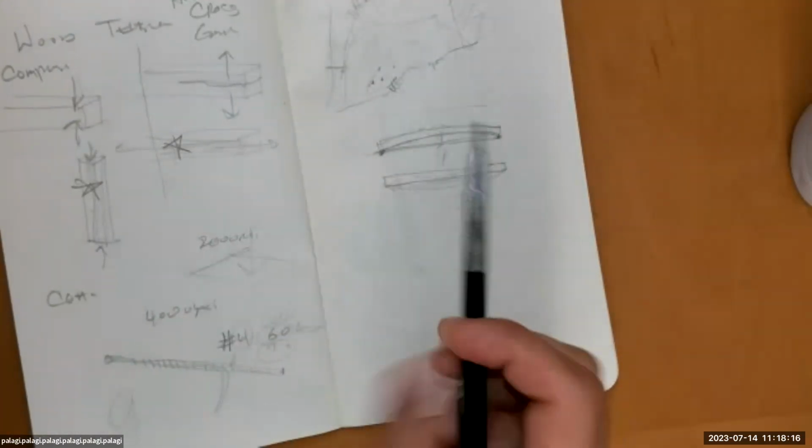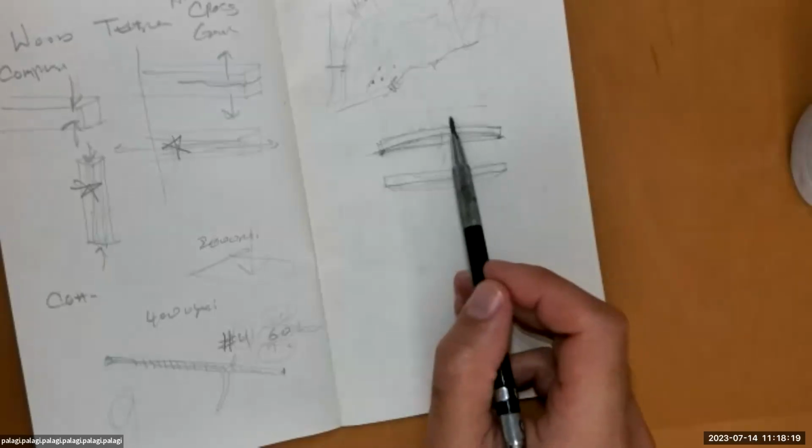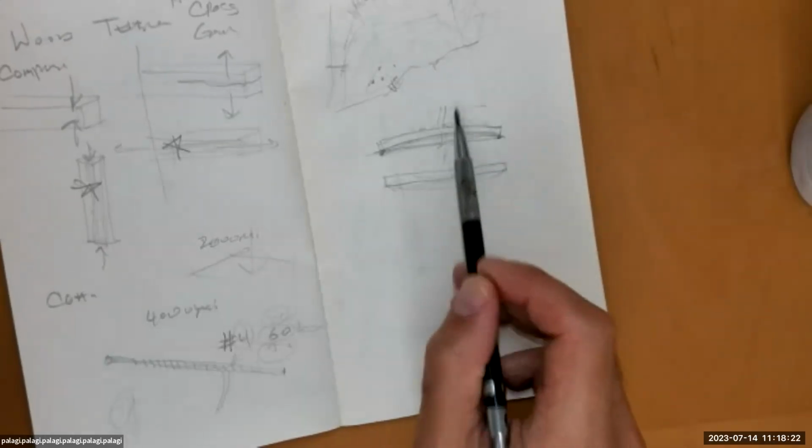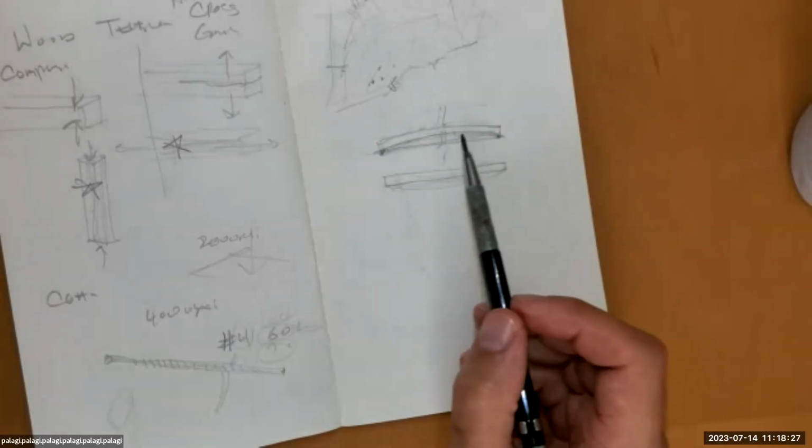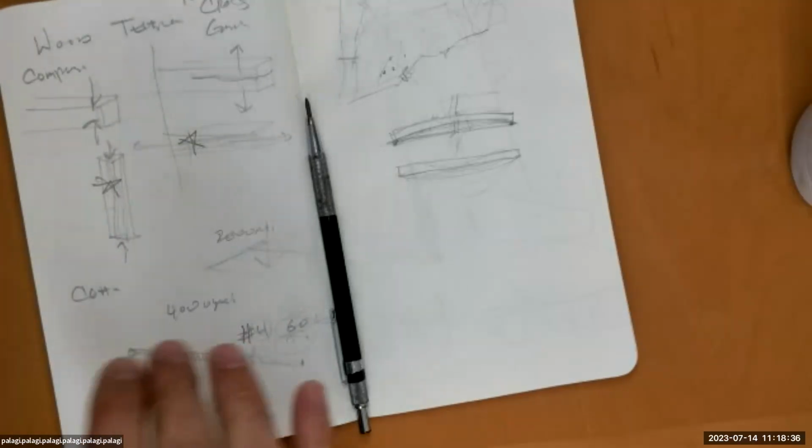So it's kind of interesting. I never really thought about it that way, but both glulams you might order with a camber, and steel. You'd order it if it's big enough, and it's going to have enough dead load on it. They would come with a little bit of a pre-bend, and that is for dead load only. If it was designed for live load, it would always be flexing up a little bit, and then when people stood on it, it would go down. And when people got off, it would go up, and it would be moving all the time, right? So you wouldn't want that, right? So that's the amount of deflection. That's a whole other thing, how much deflection you want on the floor. But this is kind of big, heavy stuff that's going on.